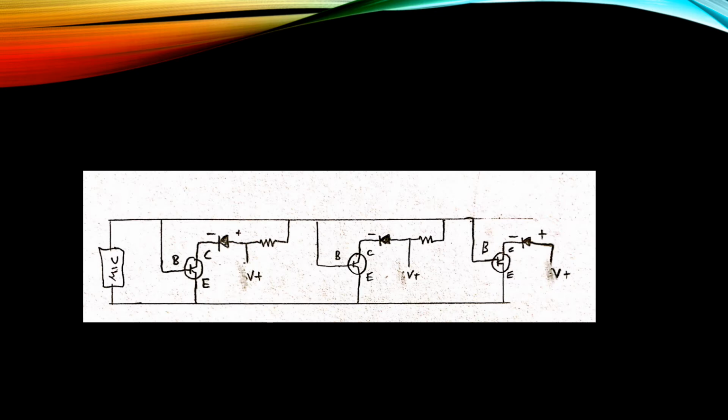So how does this device work? The mic picks up the sound signal and converts it into a voltage signal, and the signal goes to the base channel in the transistor, which opens the channel between the C and E, the collector and emitter. So more current flows through the circuit, and the lights will turn on. When there is no sound, there will be no signal going to the base and the lights will be off.